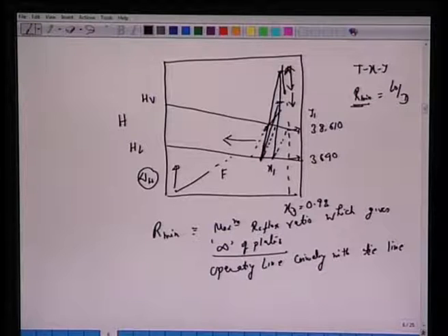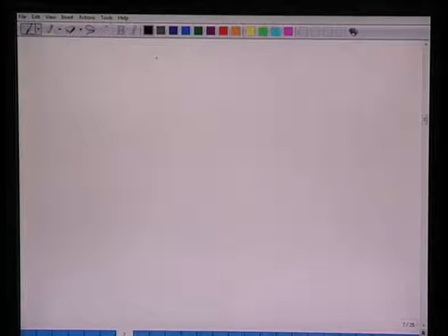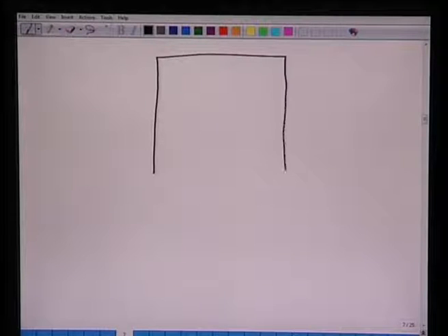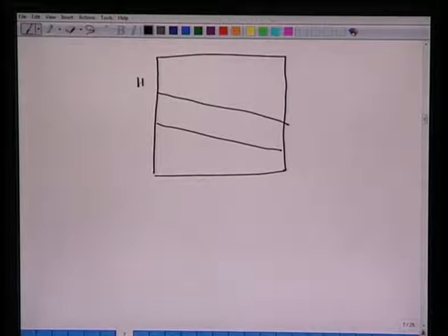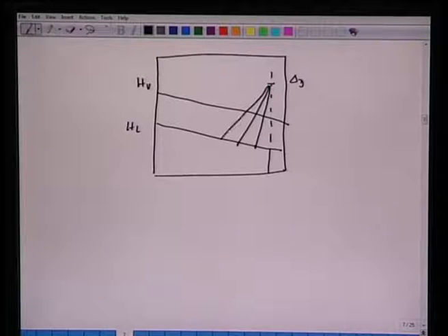So if you do this again on this HXY diagram, we said that there is a possibility of a certain tie line. Let's draw again here, we have some arbitrary del D point here, and we are connecting all these points which would become our operating curves.